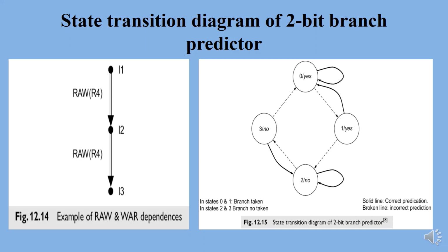One possible organization for this branch prediction memory is in the form of an array which is indexed by low order bits of the instruction address. If 12 low-order bits are used to define the array index, for example, the number of entries in the array is 4096.